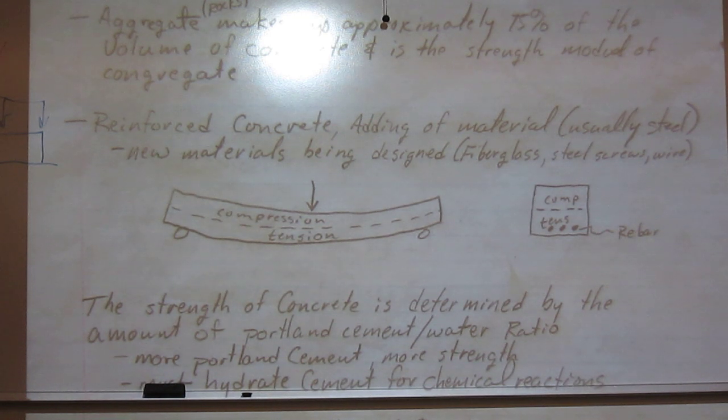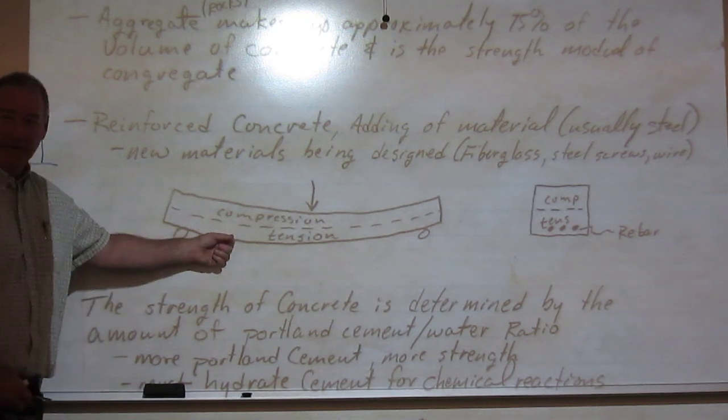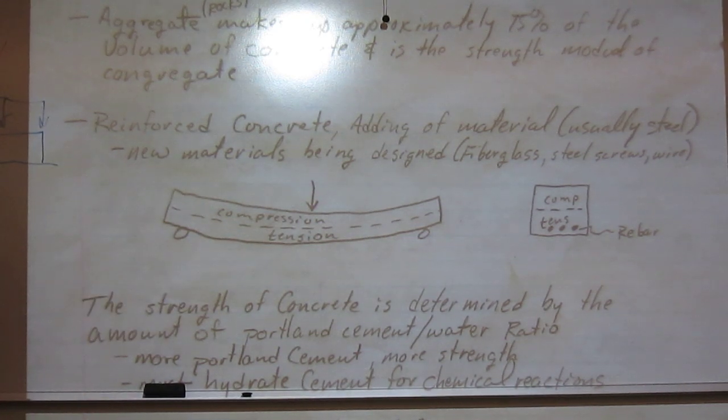So it's just that when you use it for a structural sense, that we really got to be careful of this. Okay. So there's a difference there. A slab like a floor, which is a platform for occupant use, we talked about that yesterday, that's not really a structural item, right? It's the joists and the decking that are the structural items. Does that kind of make sense?